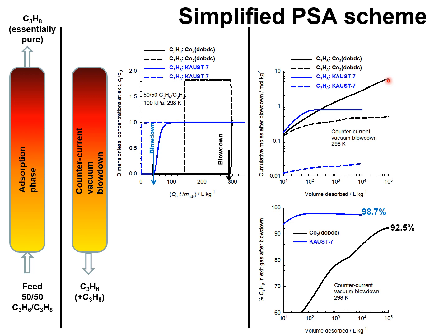We note that with cobalt MOF74, a significantly higher amount of propylene is recovered, about 5 to 6 moles per kilogram of adsorbent, but concomitantly we have a significantly high amount of propane also being recovered in the blowdown phase because of the significant amounts of propane that remains in the adsorbed phase at the start of the blowdown operations.